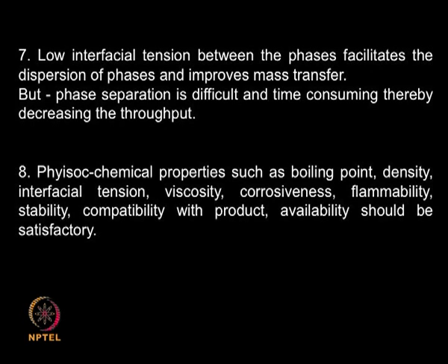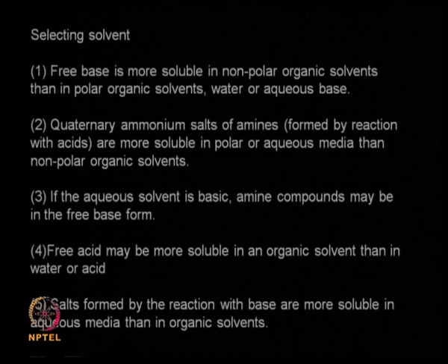that means you should not use solvents which are highly flammable or have very low boiling point, because a lot of solvent will vaporize during your handling and you will be losing solvent as a vapor, and also you will be having possible explosion hazard or flammable hazard if the solvent goes into vapor phase. The solvent should not deactivate your metabolite or protein of interest, so it should be compatible with the product. So we need to select a solvent which satisfies all these conditions.